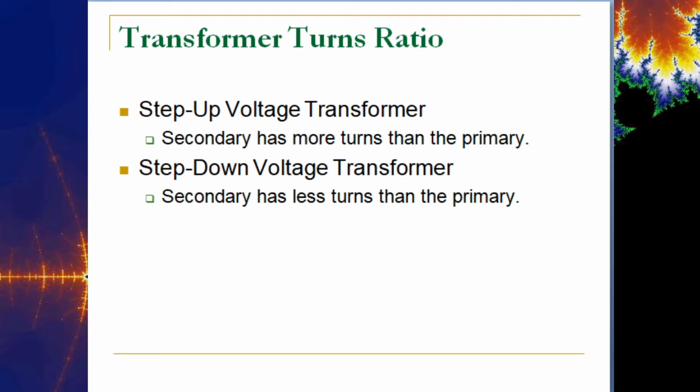And remember, the reason why is because an inductor does not have an instantaneous change in current. So what happens when you have a short? The current goes through the roof, right? Especially if you short everything out, if it's a complete short, you have massive, massive current. So that coil is going to take time to change from whatever current it was at to this new current it's being asked to jump to, and it's not going to be an instantaneous change on the secondary.